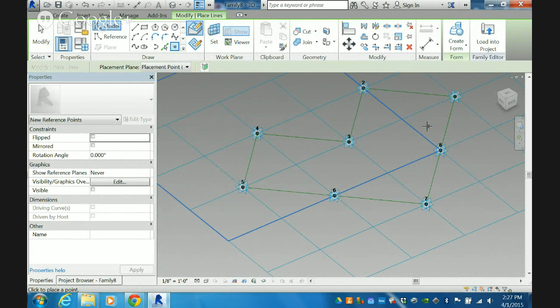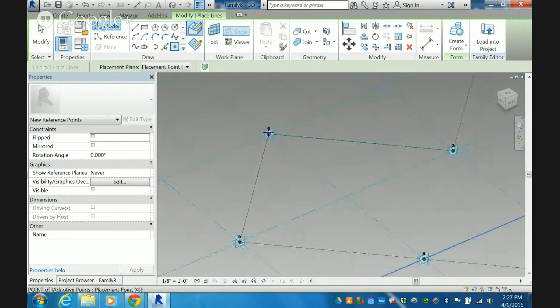If I was to level everything based off of that first node where its XY plane existed, all these other values that we drop in will also exist on that same plane. So if this pattern gets applied to a curved surface, it's going to mess up all those other nodes we're going to place. That's one of the reasons, and it seems tedious, that I'm dropping these points in plane per plane.